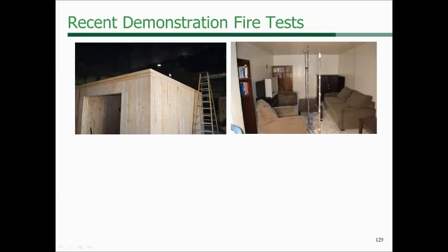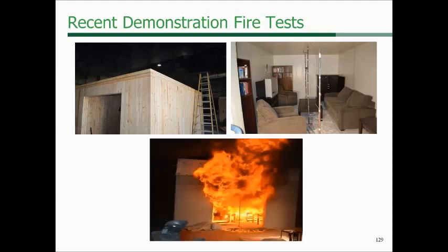And it was packed entirely with furniture, the fuel that would create the fire in this example of a residence, using the 95th percentile of the actual requirements for E119 for exposure to fire, providing that fuel. And as you can see in the test, there was an extreme amount of fire that occurred because of the amount of furniture and such in the actual room.